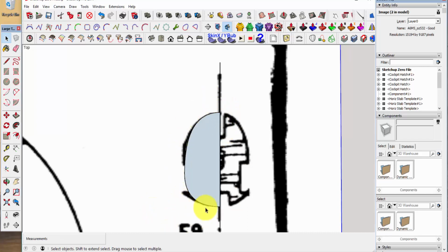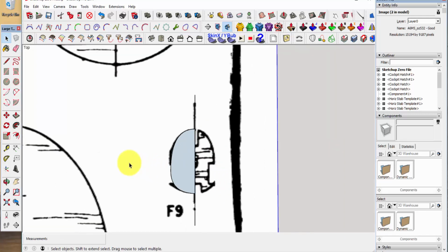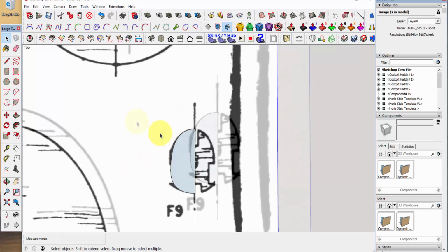We've created a face or a plane. So this is the plane or surface that we're going to use for F9, and we've kind of used a bastardized version here, halfway between the skinny one over here and the thick one over here. But because we're working with foam, this is going to be easily manipulated so that when we shape the fuselage later, it's going to be a real piece of cake to make sure all these curves conform and flow correctly.